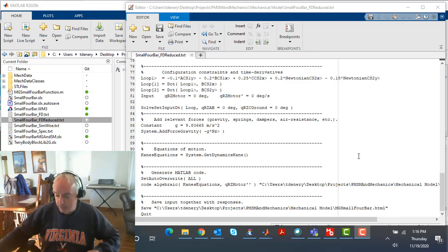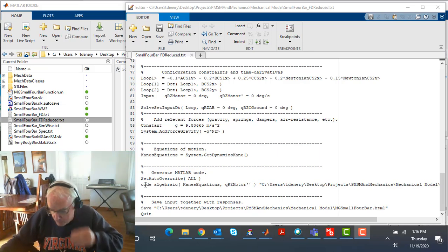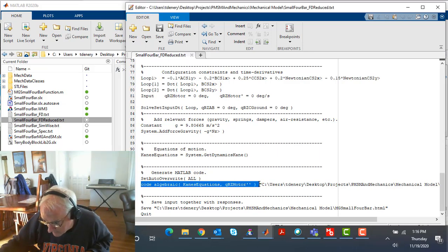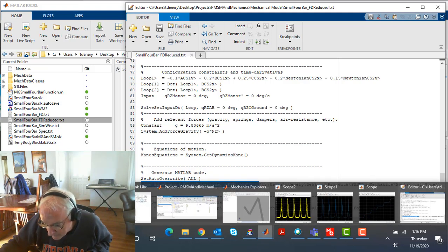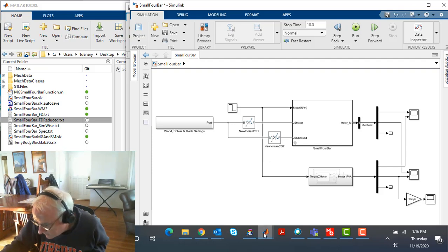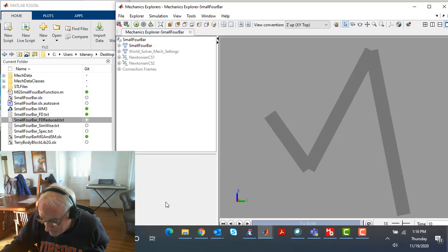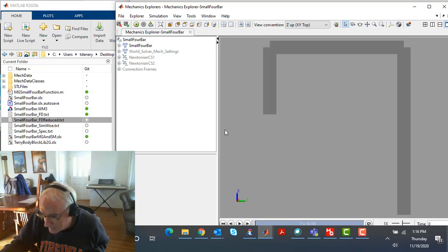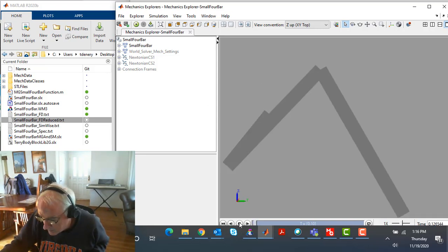So anyways, with regard to our input deck for MotionGenesis, this is the key point right here. Instead of solving for the torque, we're solving for that angular acceleration. And let me show you my use of that code in the model we have right here. I think I'll run the model first, all right? And let's maybe run it from the Explorer, and we'll just hit run.